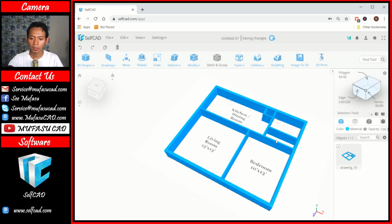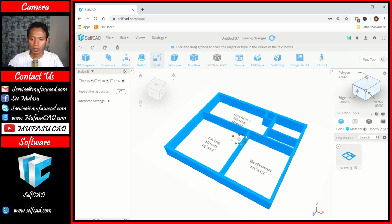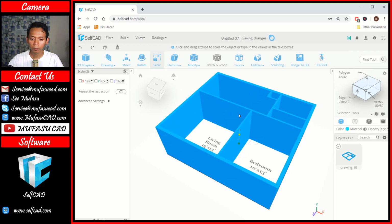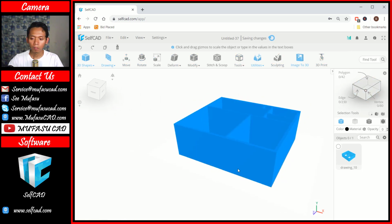Okay, it will be automatically converted into 3D models. I will use a scale command to scale this object. I will use the green axis and we can move to the top. Okay, we scale these models. And next I will create holes for windows and then for a door.